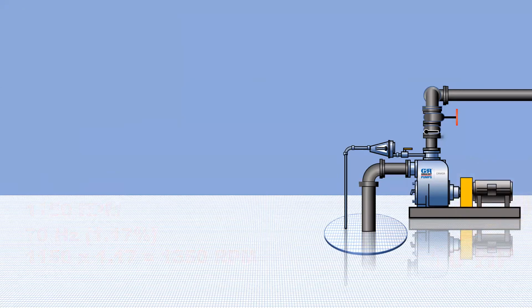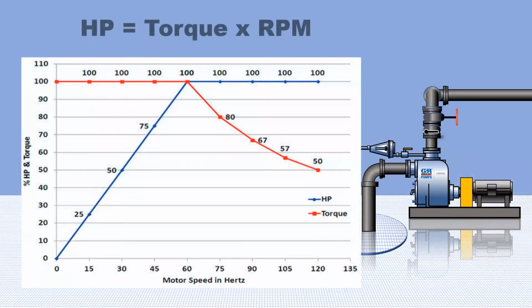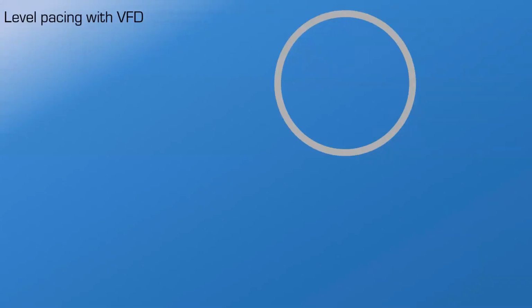That's right. And then your VFD can be sized for 10 horsepower, and your motor is 10 horsepower instead of 15. Okay. So again, this chart that you spoke about before, we can see that blue line remains constant after the 100% or 60 hertz. Yep. Okay. So let's take a look at another example. That was overspeeding in order to achieve a duty point.